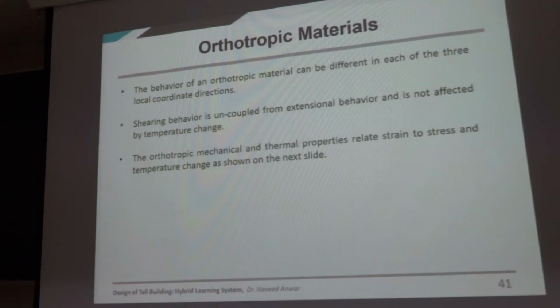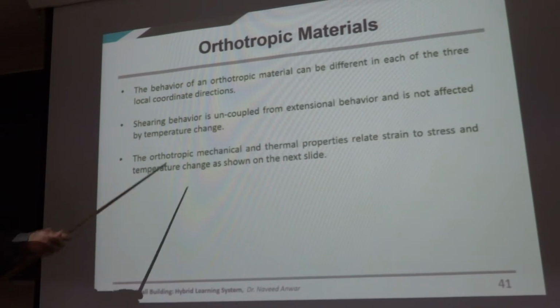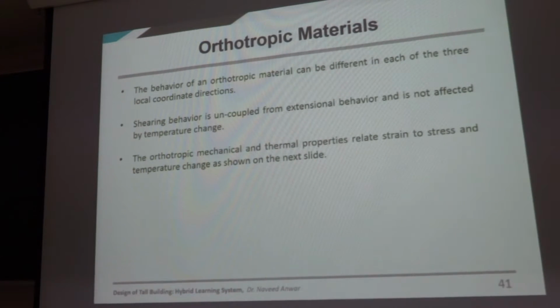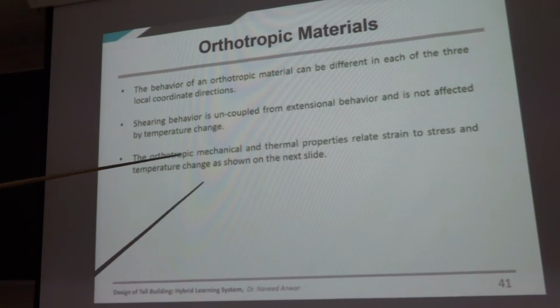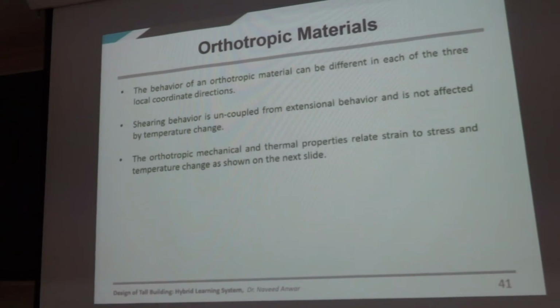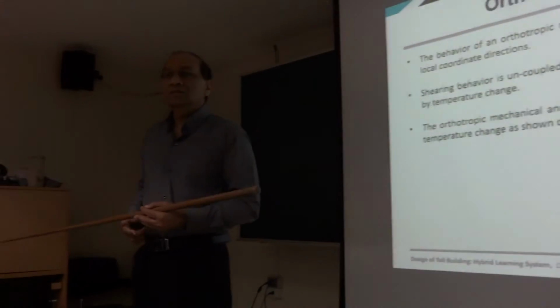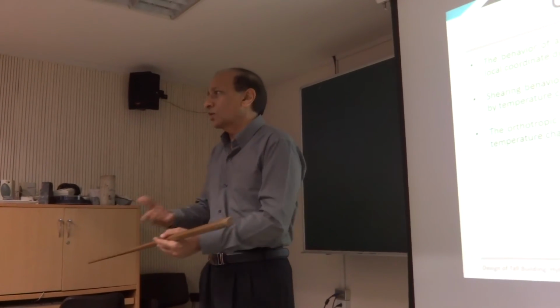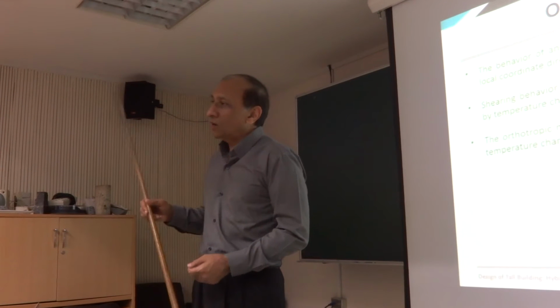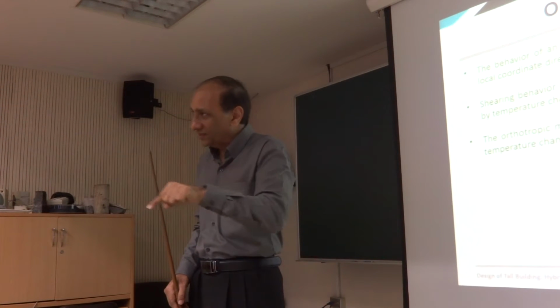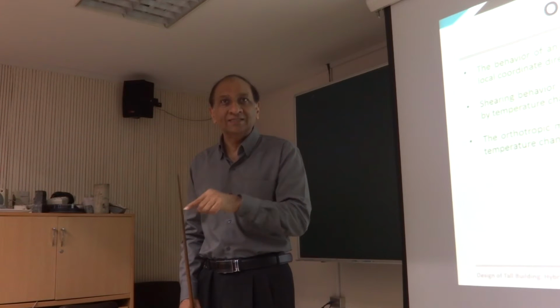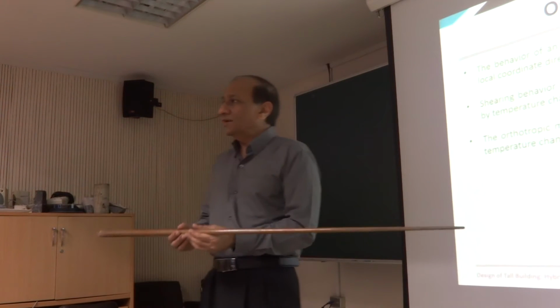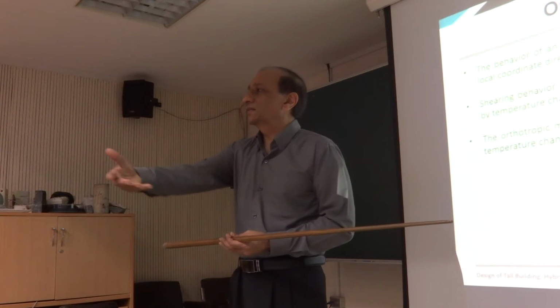Understand that. Orthotropic. What is an orthotropic? We also talked about it a little bit. Now it's time to understand it in a little bit more detail. Orthotropic materials are those in which the properties in two perpendicular directions are not the same. Let's say you are modeling a slab, right? And there's a concrete in that slab. Now the whole reinforced concrete in that slab is orthotropic, because in one direction there may be more reinforcement than the other direction.